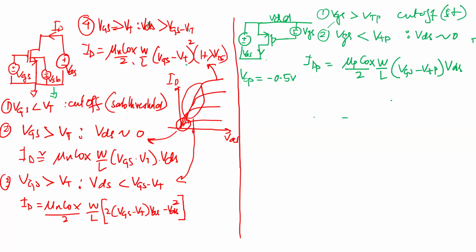And if you preserve the sign, then obviously the negative cancels, and IDP is the direction of the current flowing from the source to drain. That needs to be positive. If you do drain to source, that needs to be negative, and then you need to flip it. Okay. So just follow one convention you're comfortable with and stick to that, at least for your own design. But you should know the direction of the current which is flowing.